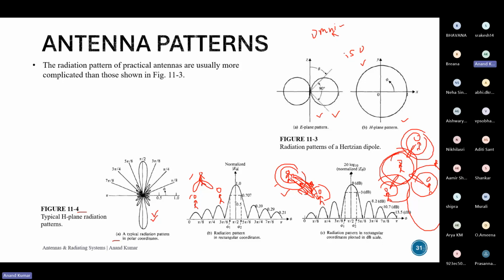And they could have a device as well. So we are just three friends, so we will all have devices with antennas whose patterns look something like this. We are radiating high power in only two directions, and in the remaining directions we do not radiate much power. I hope you can follow. So based on the needs, you can design your antenna to meet a certain type of pattern that you want.